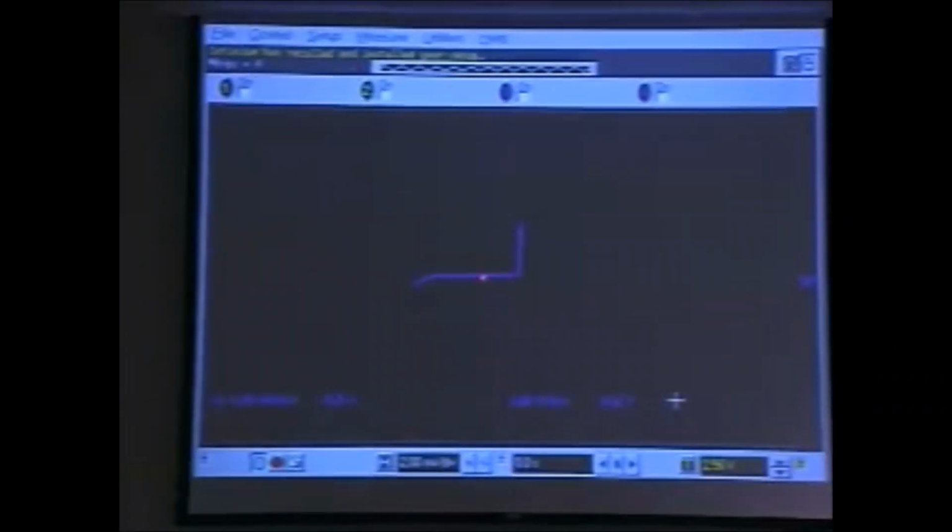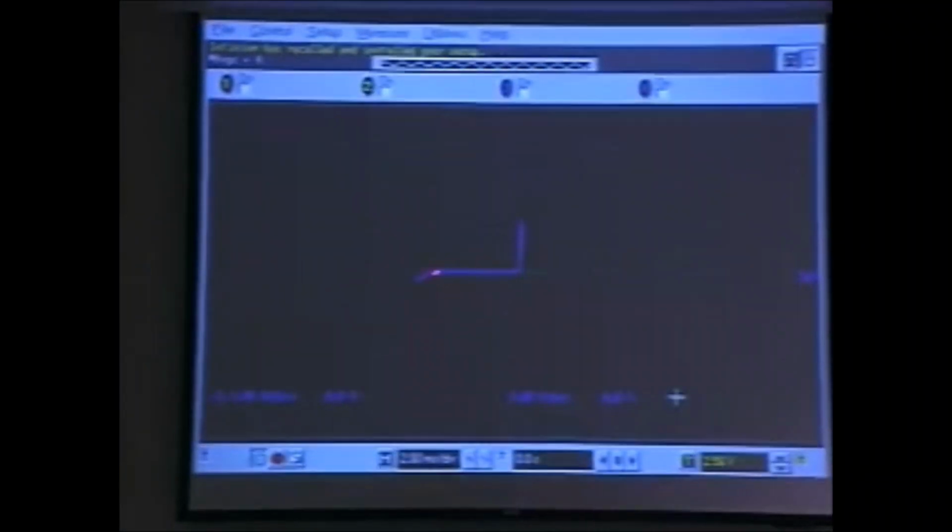I can't change it. Number 3, I have another lumped element called a Zener diode that you will see in the 4th week of this class. The characteristics for the Zener diode look like this. If the voltage across the Zener diode goes up slightly, the current shoots up. But if the voltage becomes negative, I don't have any current flowing through it until the voltage passes some threshold, at which point my current begins to build up. So that's another interesting lumped element called a Zener diode.